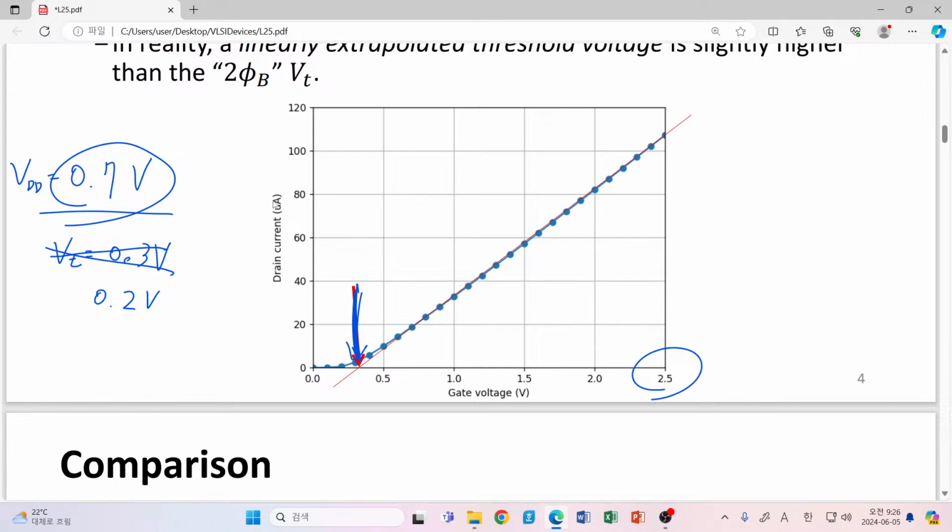Then, well, let's think a little bit further, the case where you introduce higher doping density. So think about the effect of introducing higher doping density in your device. If you introduce higher doping, then of course your threshold voltage will be increased, so you will have this kind of behavior. However, you have also one effect I told you before.